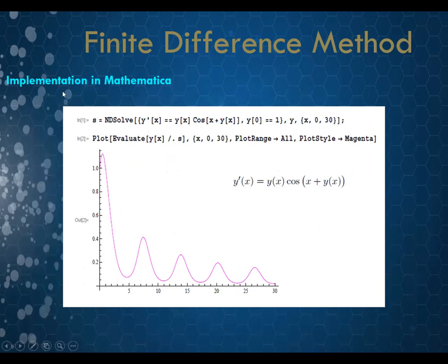For implementation in Mathematica using the finite difference method, it is sufficient to use the NDSolve command. That is, it uses the finite difference method and the finite element method and switches between them adaptively based on the form of the differential equation. For example, it is shown here the solution of this differential equation with the boundary condition y at 0 equals 1. And this is the solution of this differential equation by the finite difference method.